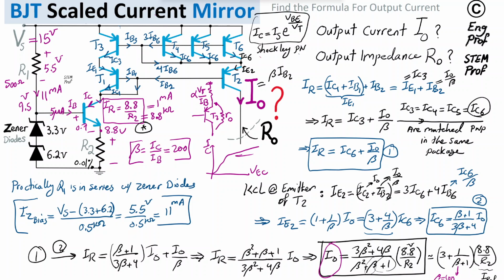So in the range that we are utilizing in the IV curve, there is a slope. It's not a zero slope. It's a non-zero slope for a practical transistor, and the value of this is basically R out. If it is perfectly horizontal, it means R out is infinite. So R out is a finite value, indicating that there is some slope here. That R out is from the early effect, which is early voltage divided by the DC bias current of that transistor.